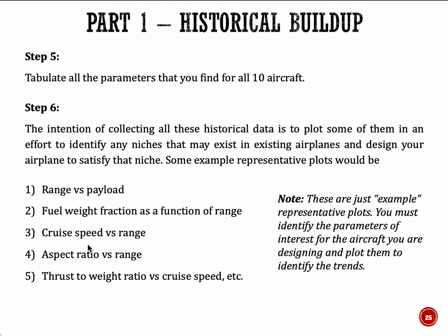You really have to identify what parameter is of most interest to the type of aircraft that you're designing, okay? Right? So again, as I said, these are just representative plots. You must identify the parameters of interest for the aircraft you're designing and plot them to identify the trends. So it's very important for a long range aircraft, endurance will be more important, right? The flight time will be more important. So you may have to plot that versus like payload, or takeoff weight, right?